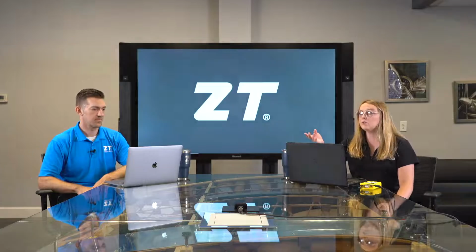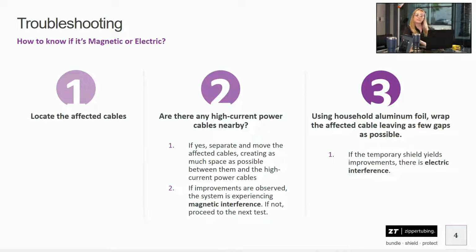Okay, so now that we kind of know the two types, how do you know what you have in your system? We've got a few pretty simple steps that you can take to identify. First thing you're going to do is locate those affected cables. Figure out what's giving you interference, what you're seeing problems with, usually a signal cable. And once you've identified that cable or component, you want to determine if there's any high current power sources nearby. If there is, you want to separate your affected cable from that power source, as much distance as possible. Like we talked about, it diminishes that interference with distance.